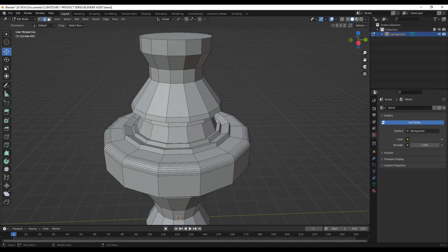Now if you wanted to create more loops by yourself, say you've already shaped a mesh and then you want to make more loop cuts by yourself, we can simply use the loop cut tool. So two ways we can do this. You can come over here and then you can hit this loop cut tool. Once you select it and go around your mesh, it will require you to place it at a starting position. And so if you left click here and then you drag without releasing your mouse, you drag this to this point, and then when you leave your mouse, that cut is made there.